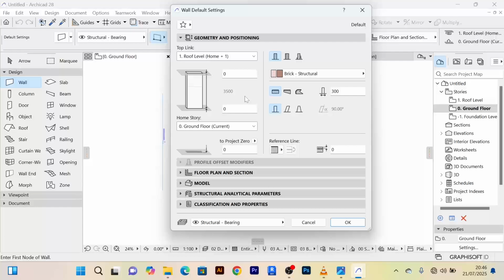It is perfect. And here we want our wall thickness. This is the point where you can give the thickness. I want the wall thickness to be 200 millimeters. Our measurements are in millimeters, and it will be seen as meters. The software will read it as meters, however it is in millimeters.